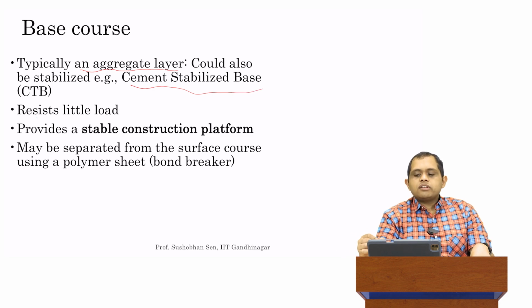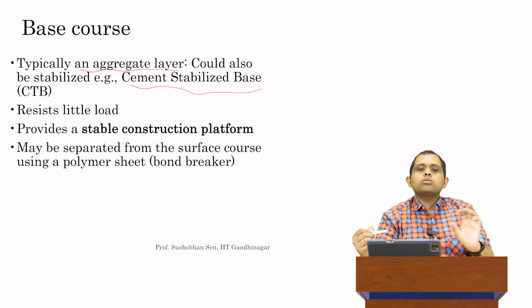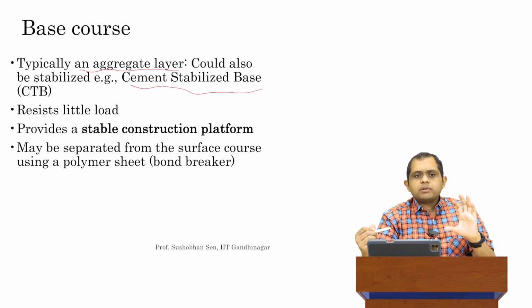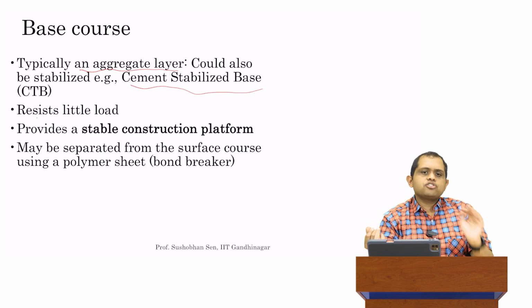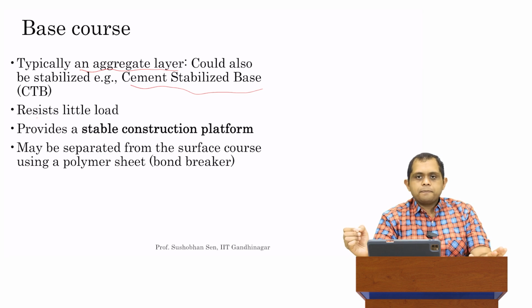As a recap, what is cement stabilized? So basically, you have some soil, you have some aggregates, and to that we add cement, but in a lower quantity of cement and a lower amount of water. So we don't get as much strength, but we get some type of stabilized layer which is not as strong as the surface course, and that we call a cement stabilized layer.